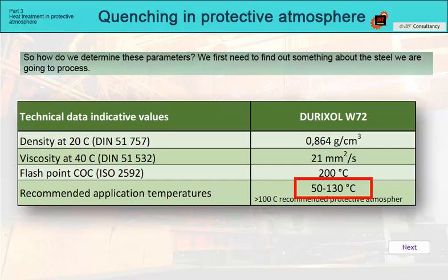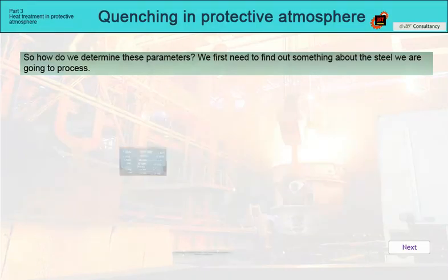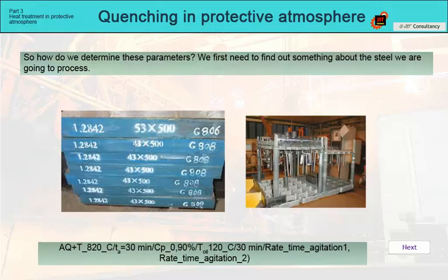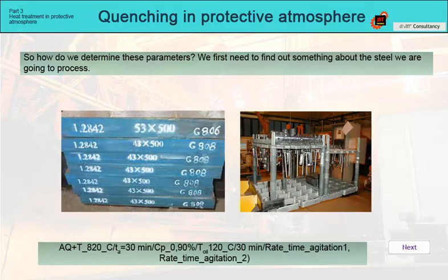We will set the heating time according to our experience with the given furnace. The holding time for austenitizing will be 30 minutes. The holding time in the quenching bath will also be 30 minutes. The oil agitation will be intensive for the first 5 minutes, the remaining time slow. However, the setting range depends on the furnace capabilities and batch parameters and can be very individual. The resulting work procedure will be specified in the production order, for example, in this way.